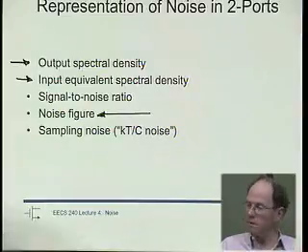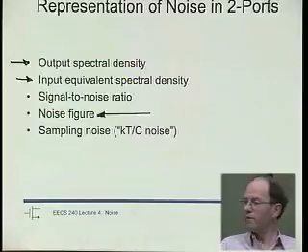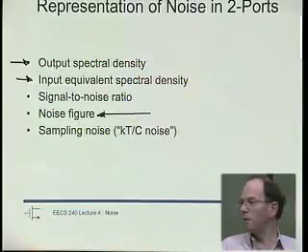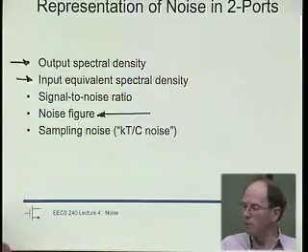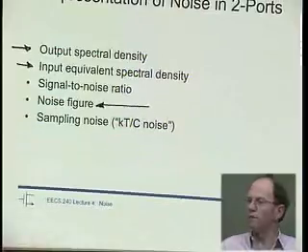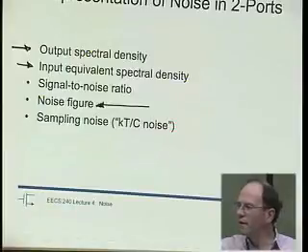Once the signal comes out the other end of the LNA, the signal-to-noise ratio has dropped from 20 to 20 minus 2.5 or 17.5 dB. And then you go into the mixer, and it also has a noise figure, 5 dB and so on, right? And ultimately, you can determine whether, once you come out the other end of your receive channel, you actually still have a sufficient or positive signal-to-noise ratio.